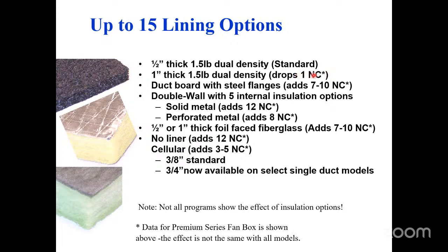In reality, it's not even one. The manufacturers that tested this, specifically the guys at Krueger, I know tested it, they rounded it up to one just to get it to a nice whole number. It's even less than that. So there's probably not really any reason to buy 1 inch thick insulation. Just take the 1/2 inch default. It's good. You can also do other stuff.